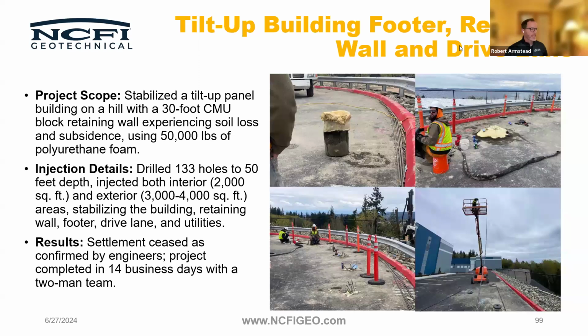I got an excellent tip, and that was actually from Jerry Sargent from Slabjack Geotechnical that did this project on the screen, was that you can actually notch those really deep pipes out rather than knocking the tip out. Oh yeah. Perforated, kind of like a tributary. Or at least at the ends, being able to provide some tube notches for escape. Excellent tip, Jerry. Thank you so much. That's great.